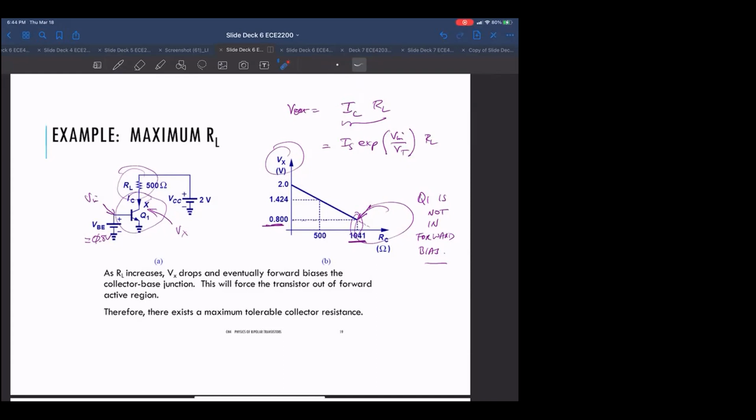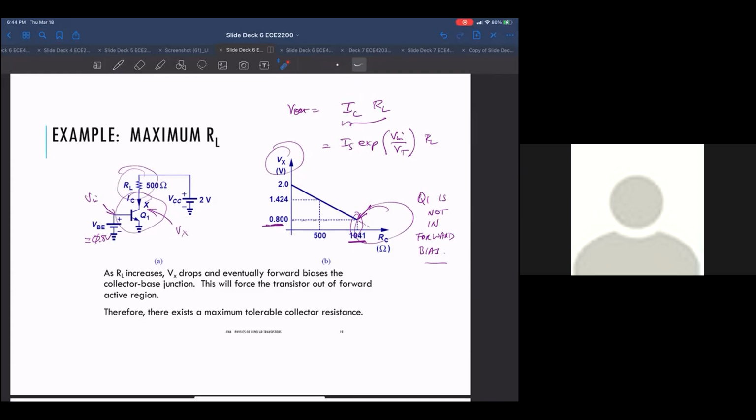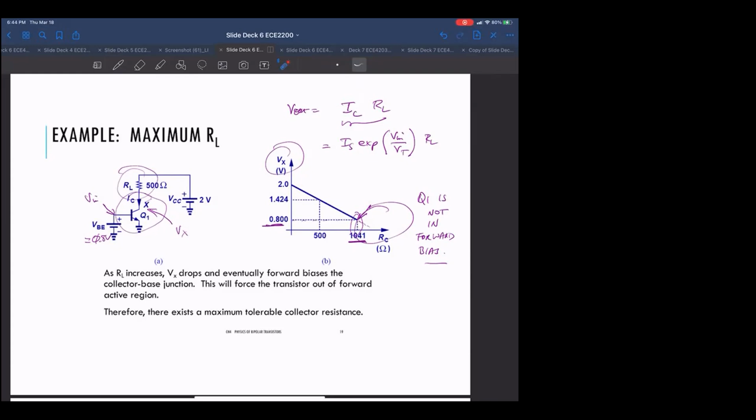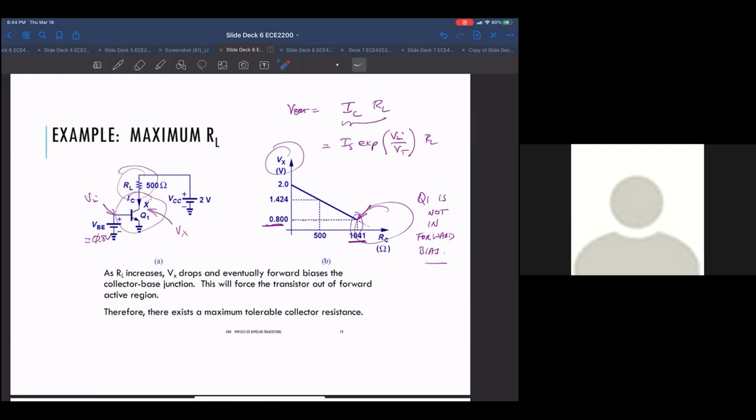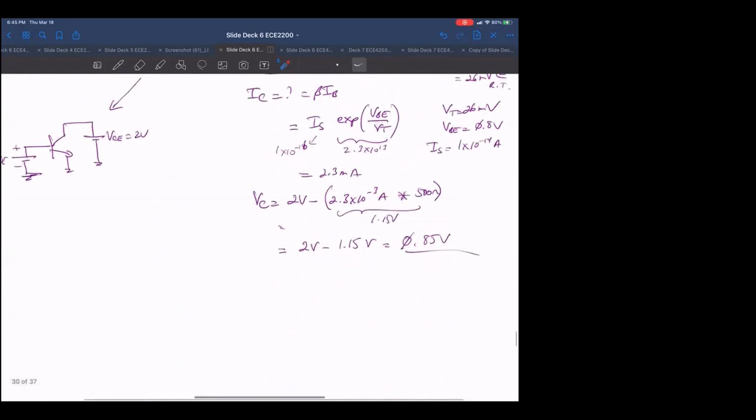But somebody else had another question. Was it Nelson? Who was it? It was me, Professor. I have a question about the emitter current. Actually, I mean about IC. So IC is going to be influenced more by the base emitter voltage than the collector emitter voltage, up to a certain point.